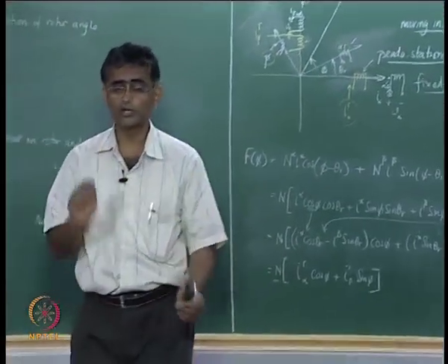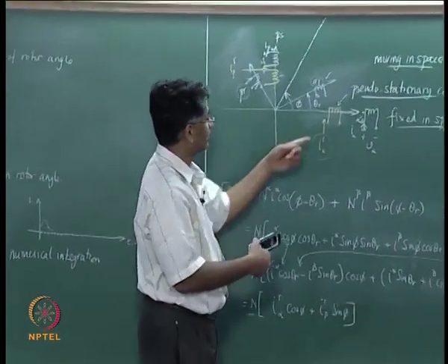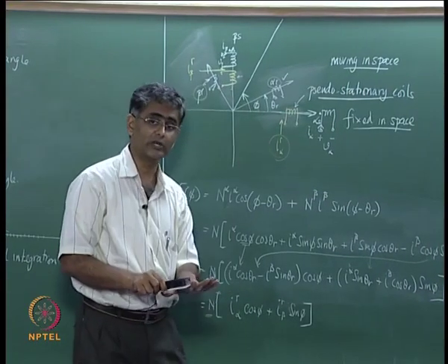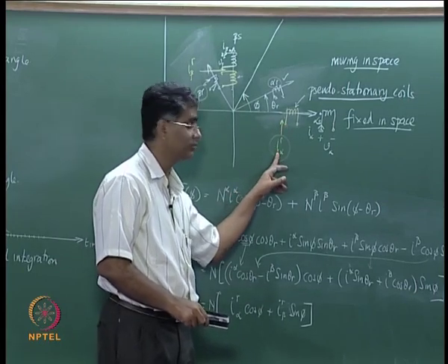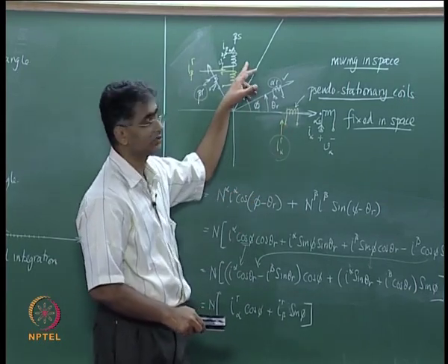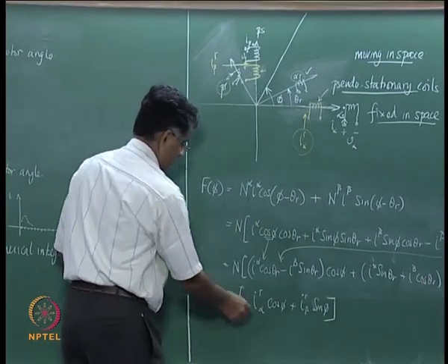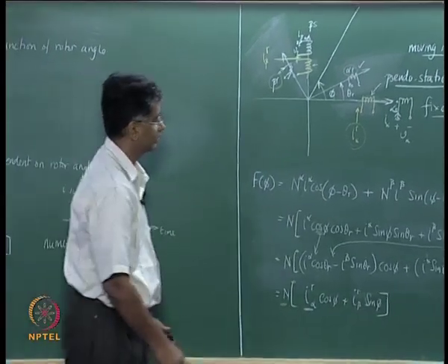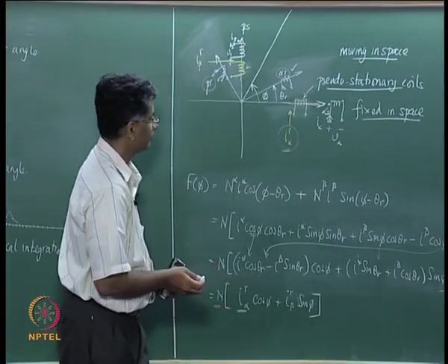It is the rotor coils that are producing the MMF, and we can imagine two more coils on the alpha and beta axis which are fixed in space, but having a fictitious flow of current through them which equivalently produces the same MMF. We give a notation I r alpha to this. Why do we call this I r alpha? Let us understand that.